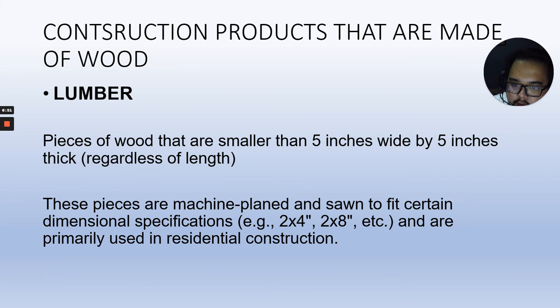Lumber. Pieces of wood that are smaller than 5 inches wide by 5 inches thick, regardless of length. These pieces are planed and sawn to fit certain dimensional specifications, for example, 2 by 4 inches, 2 by 8 inches, etc., and are primarily used in residential construction.